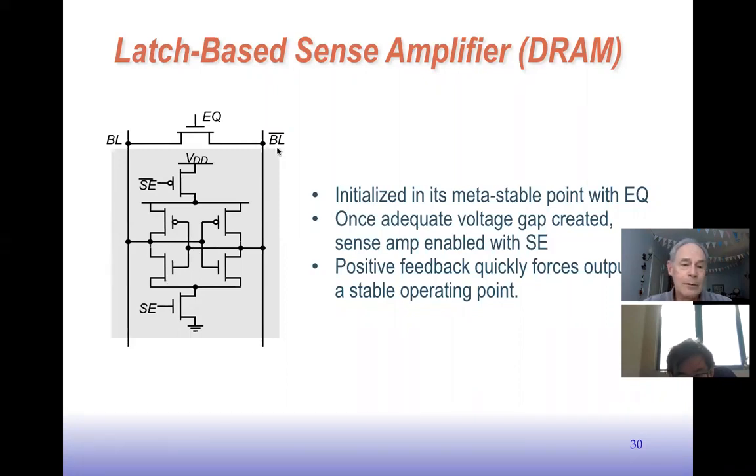And you may have noticed when I was talking about the DRAM, it's not differential cells, it's single-sided cells. So what will happen is there'd be a dummy cell or a dummy bit line that will get put between two arrays of DRAMs, right? One will be activated and the other one will just act like a reference, and that gives us this other reference here. So then we can get this differential voltage between the bit line that's active and the bit line that's just being used as a reference from another array that's not currently being activated.